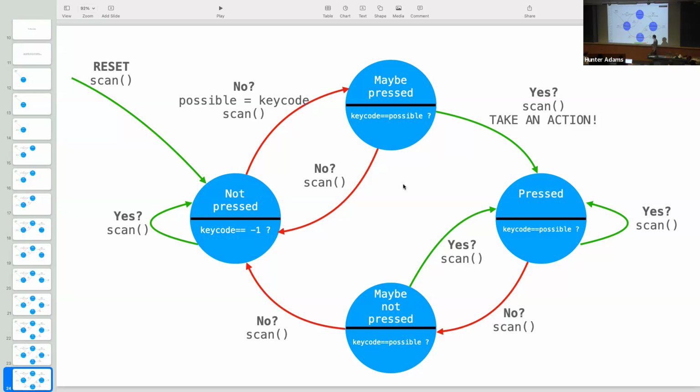In our case for lab 1, you'll have your interrupt service routine that's actually doing the audio synthesis, and then you'll have the keypad thread, and perhaps you'll have one other thread that is sort of scheduling each sound, but probably not more than that. So in this case, though we can't guarantee that this thread will be run exactly every 30 milliseconds, it's close enough for this human rate stuff that it works out okay. It's a good question.